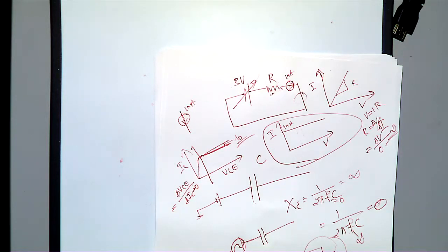That 800 millivolt is for keeping forward bias between the base and the emitter. And then this VCC is for keeping reverse bias between the collector and the base. And then this is your signal. Then you can draw, see, your DC voltage source, anyway we will be grounding. So that's the reason here you got to ground, and then this is your V1, your signal. We will not ground it because this is changing with respect to time.